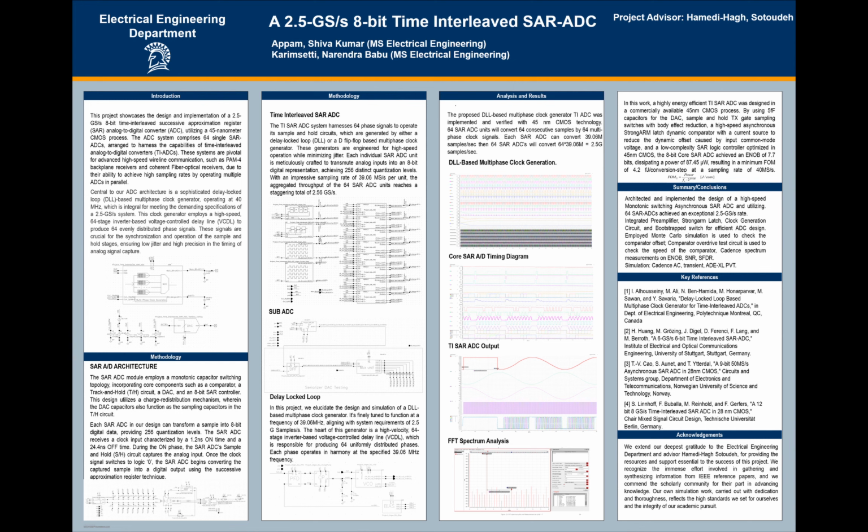We implemented these core ADCs in block level structures that have sub ADCs. Each sub ADC has 8 core ADCs, so one sub ADC has 8 core ADCs, and we have 8 such sub ADCs in parallel.